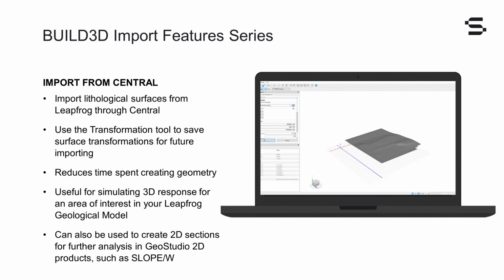For example, you may want to understand the three-dimensional pore water pressure system of your geological model prior to generating 2D sections for use in Slope W, allowing you to simulate the slope stability of your Leapfrog project using pore water pressure data. In this video, I will step you through the basic steps of importing your surface meshes from your Leapfrog geological model into Build 3D.